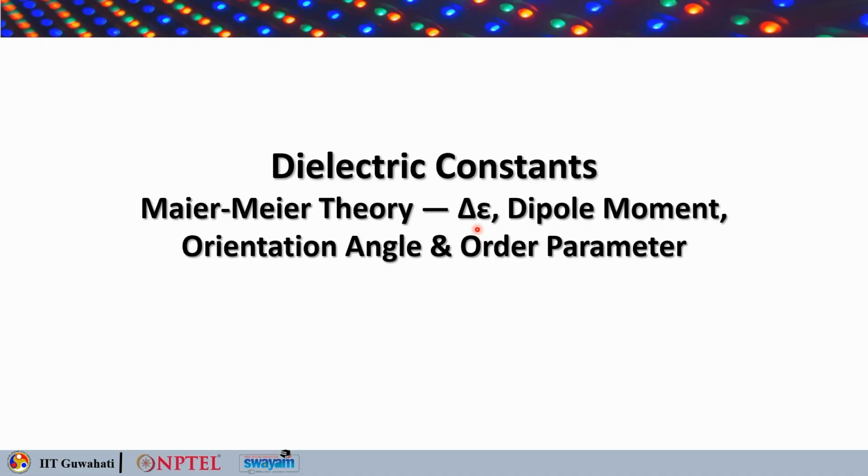And the sign of delta epsilon determines whether the liquid crystal is suitable for twisted nematic or in-plane switching. When it is positive, it is either twisted nematic or in-plane switching, and for vertical alignment the delta epsilon will be negative. So, those modes can be determined.